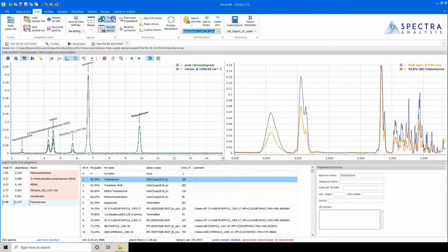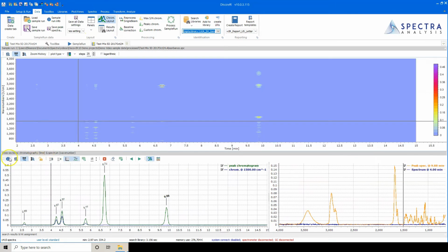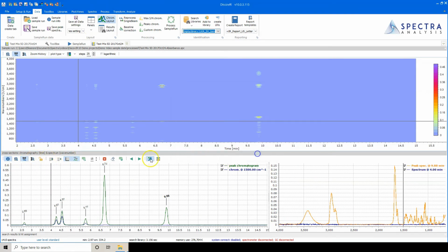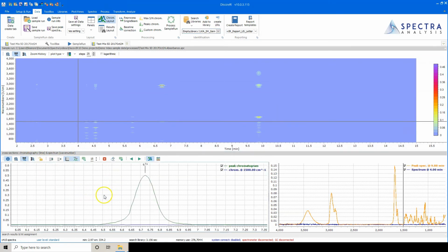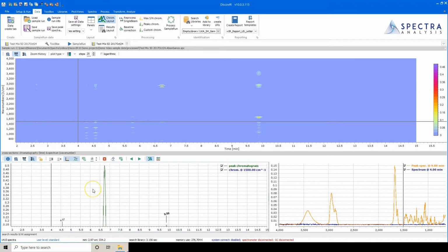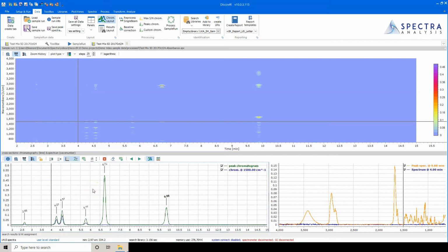For controlling the plots, first look at the blue information button on the bar above the plots. Combined with the other buttons here, the user has lots of options. Using the horizontal or vertical direction buttons, the user can use the left mouse button to zoom. To unzoom, the user need only press the right mouse button. Note that when the plot is unzoomed, it is auto-scaled so that the whole CG spectrum is shown. To avoid this, lock the spectrum prior to zooming the plot.